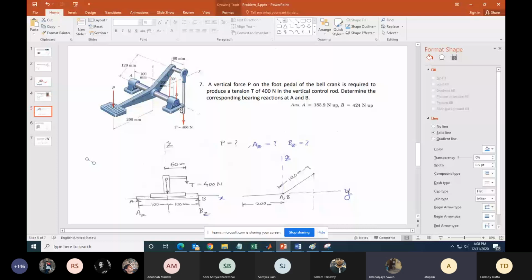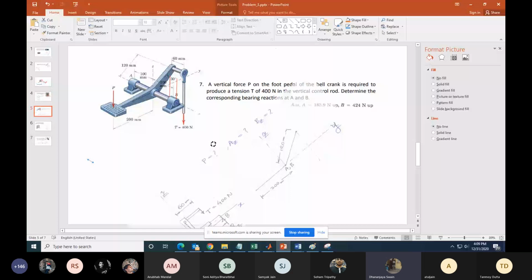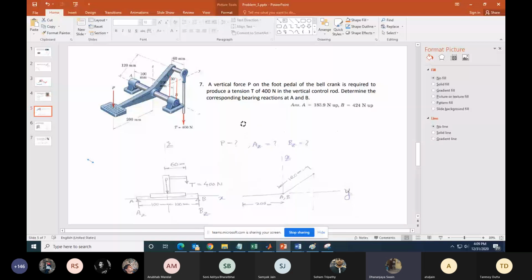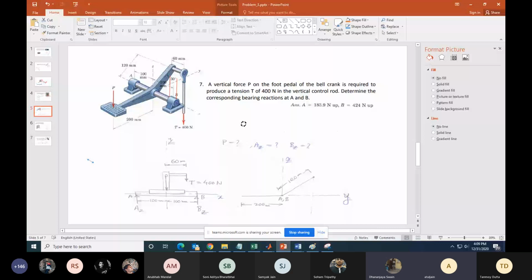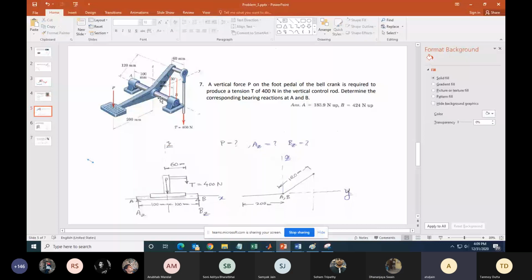Sir, about the AB axis, it cannot rotate still. About? Yes, about. That's why you have AZ and BZ, which is the net reaction moment, if it is possible. Because you cannot rotate. So essentially, you are saying this cannot happen. It cannot rotate like this. Sir, but for translation movement, we used to take different restraint, and for rotational movement, additional moment restraint. Only look at one constraint at a time. If you look at only one constraint at a time, it is allowing to rotate.